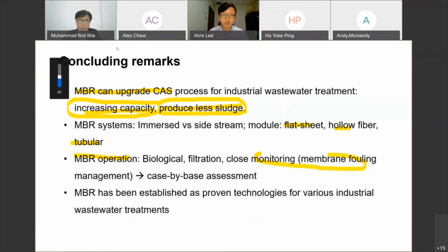It is from Jeffrey. What is the impact to the membrane? For example, the incoming BOD is designed for 250 milligram per liter, but the actual incoming BOD is less than 100 milligram per liter. Is it difficult for the MLSS in the aeration tank to maintain 6,000 ppm? And what is the other impact to the membrane?